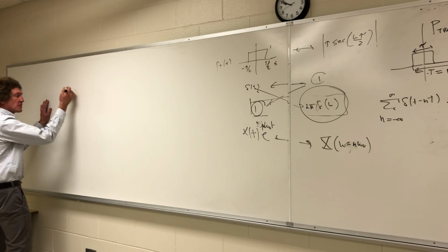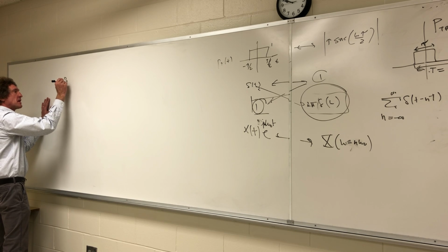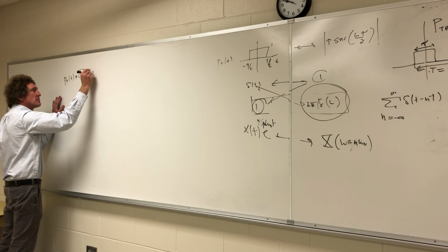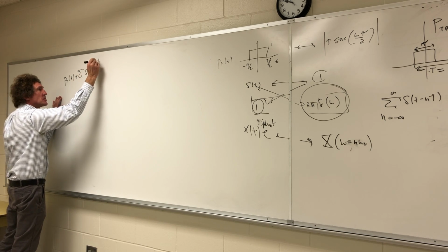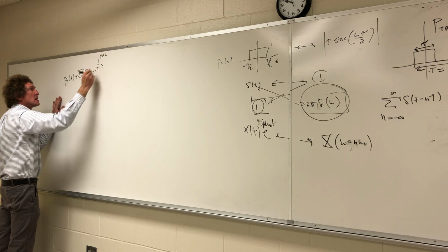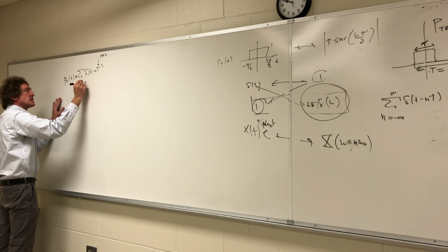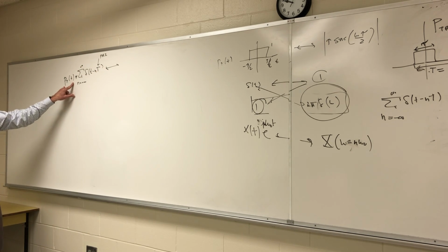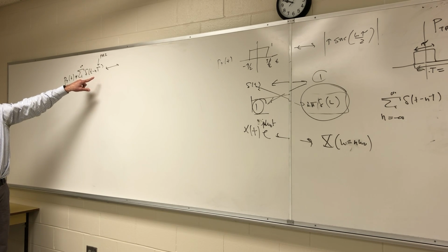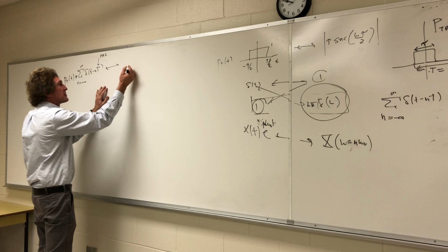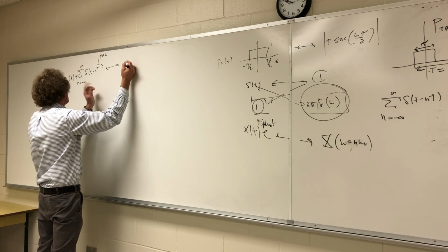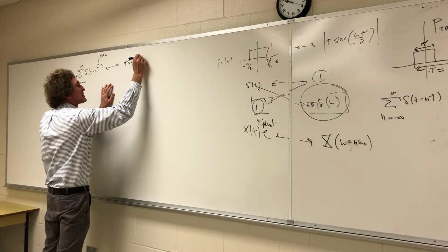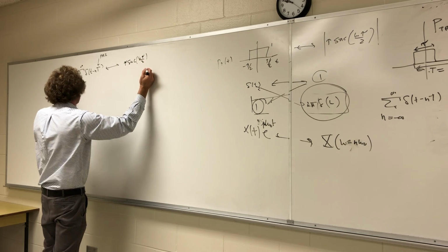When I take a look at the Fourier transform of p tau of t convolved with that infinite series of delta functions, t minus nT, capital T, and make sure you know that that is the PRI, from n equals minus infinity to infinity, and I want the Fourier transform of that. You all realize that we can take the Fourier transform of this and multiply it by the Fourier transform of that. Do you all see that, class? Now when I do that, I have tau, right, times the sinc of omega tau over 2. That's just one of them.